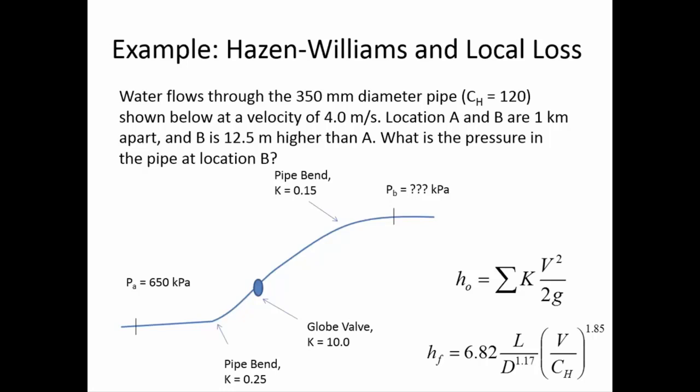First of all, does anybody remember what that bar above V1 and V2 means? It's implied when we usually use it, but what is it? Average velocity, right. Because remember that in a pipe, there's a whole range of velocities. At the center of the pipe, the water is moving more quickly than at the edge of the pipe, and so usually we don't bother to put that bar over the top of it, but it's implied. What we mean is the average velocity. I just wanted to re-emphasize that.